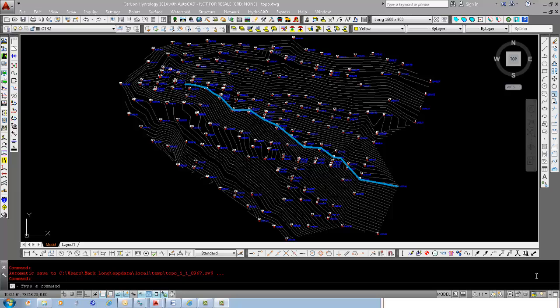To prepare the HEC-RAS input file, every channel is defined by a cross-section alignment or MXS file and the actual cross-sections or SCT files. These are used to define the channel geometry data to be imported into HEC-RAS. Also understand it's very important the stream network must have a unique stream ID and a reach ID, and together these items identify the channel.